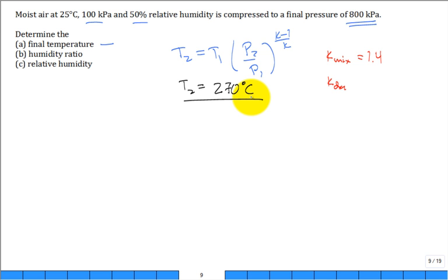No, it's not isentropic, so it's even going to be higher, isn't it? It'll even be higher. But we can use that, and what we can do is make the calculation here. What is the humidity ratio after you compress it, omega 2? How would I calculate omega 2?